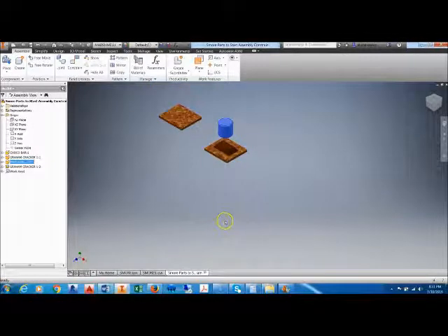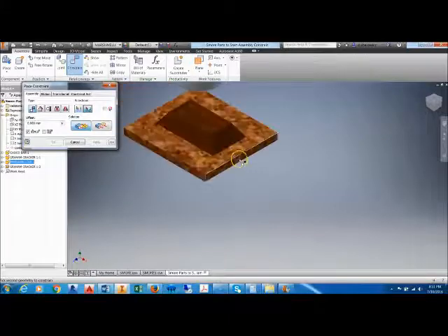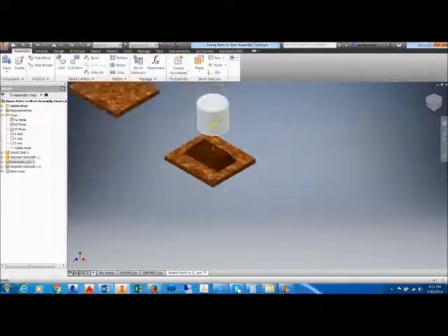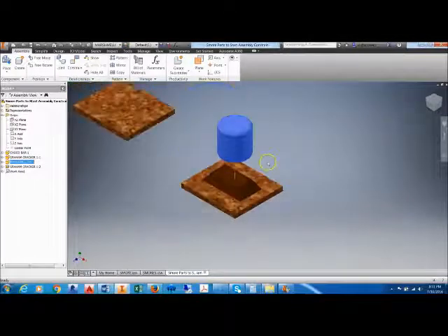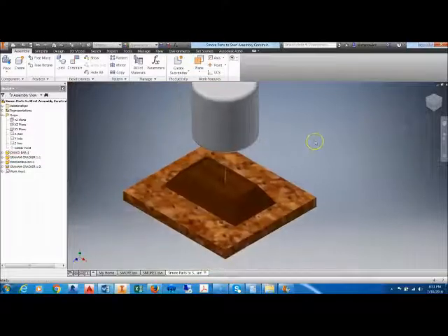So I will use that same particular axis constraint, mate to mate, and select that axis to a face, and we'll use the same exact number again, where that will be negative 28.5, and that sends it to the center of my assembly. And you can see now that the marshmallow is now fixed to the center of the assembly. However, its height has not been fixed. So I now need to set height for the marshmallow to touch the top of the chocolate bar.